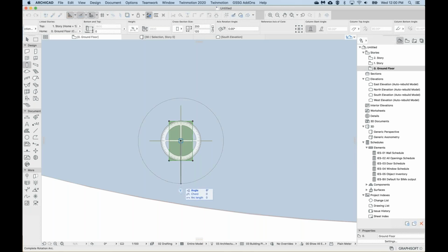So Y axis, and I'm going to drag my cursor around and then hover my cursor over the edge of the shell until my cursor changes from a pencil, and it should turn into a right angle. At some point it will turn to a right angle. Once it turns to the perpendicular symbol, I click, and that will make this perpendicular to that edge.